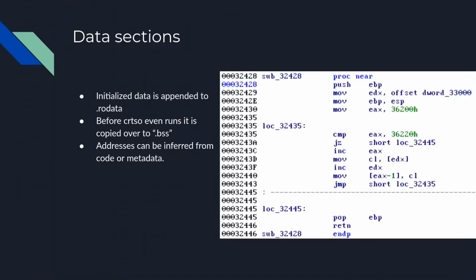And it's very simple. It just copies a bunch of RAM. So they don't have support for initialized data sections. It's a flat binary. What they do is they actually use the BSS segment, so the zeroed segment at the end of the address space, and copy over a bunch of data in the program. The program itself is not aware of this. It's really in the initialization code and in the linker script.